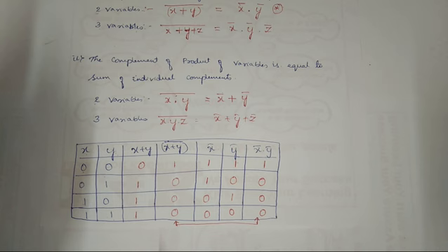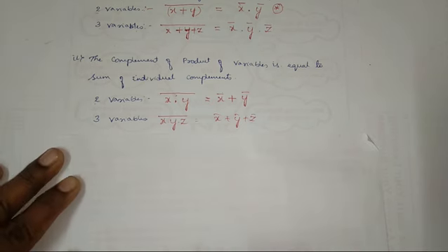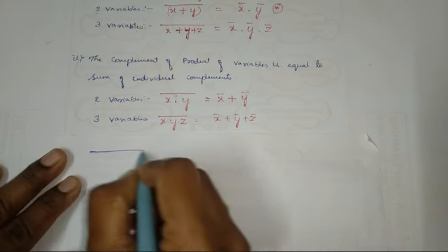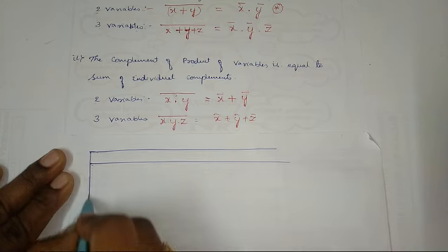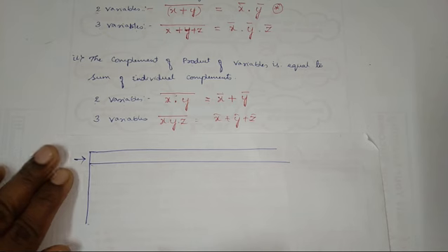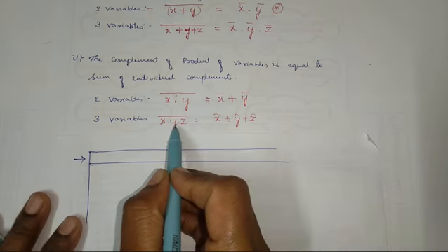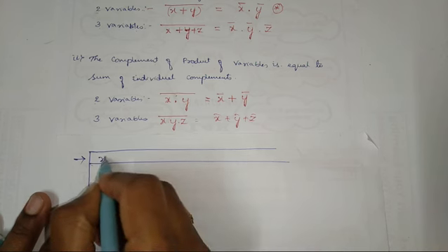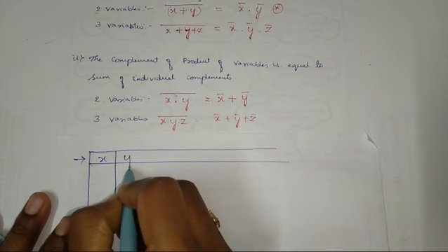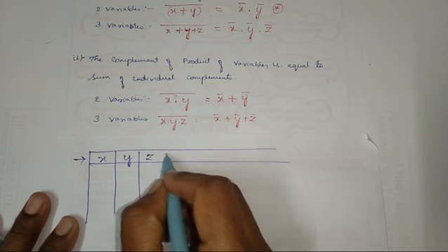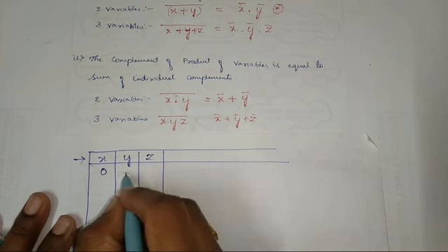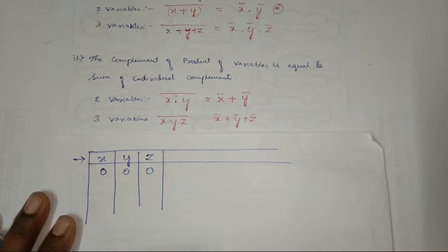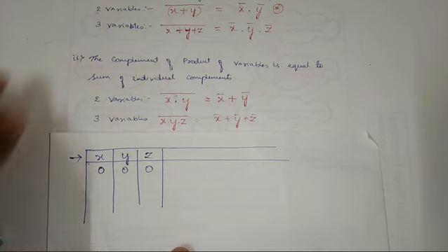Okay, how do you have to write your truth table? Let me show you. I'll write only the first row. What are the details you must enter? X into y into z. So the variables I need are x, y, next is z, right? 3 variables are there. Since there are 3 variables, you will start with all zeros and it ends with all ones, right?